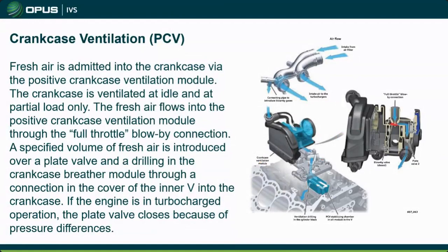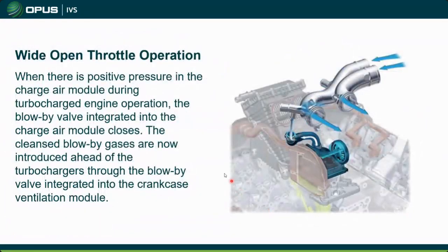So just something to know, that this thing is not always venting, and certainly not at wide open throttle, full boost. It is not going to vent. But definitely be aware that this system does only vent into that one turbo. So just know that whenever you get this thing apart, that turbo is not going to look the same as the Bank 1 turbo, and that is normal.